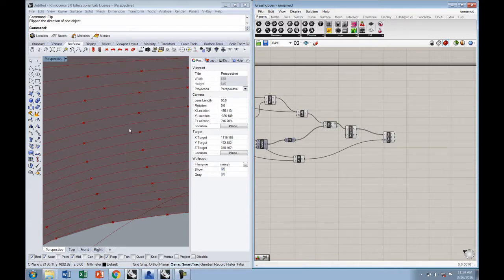And you can see over here in Rhino that every other curve is getting divided individually as I go up. Okay, so now to get the offset points, what I've got to do is do another divide distance. So I'm going to hit copy and paste, and I'm going to change this so that I'm actually dividing the B list, or the evens that are coming out of the dispatch.